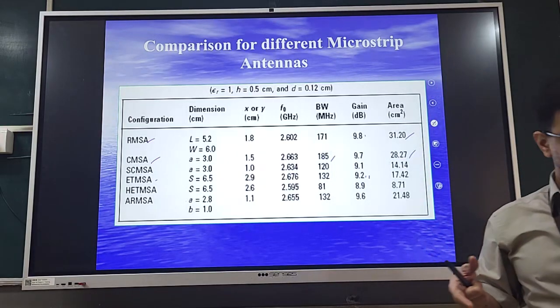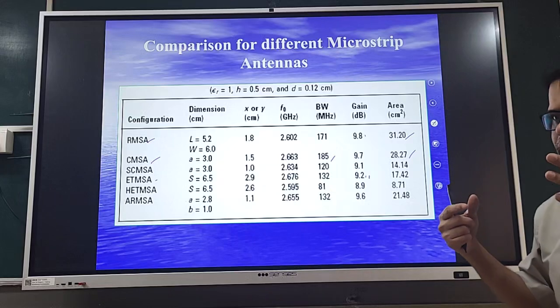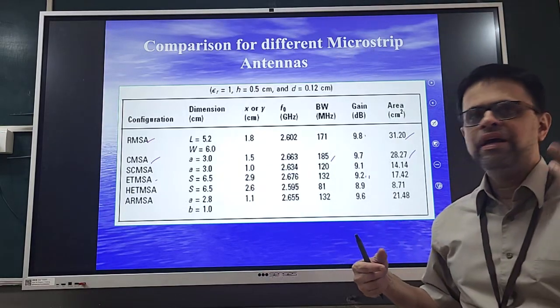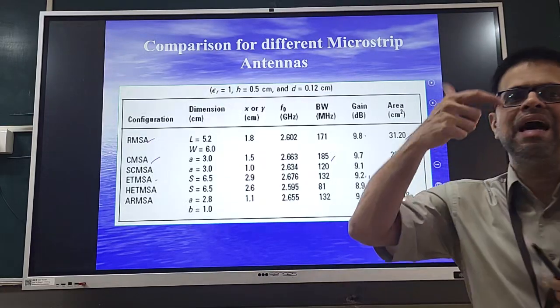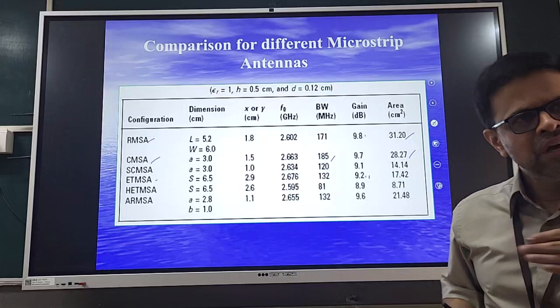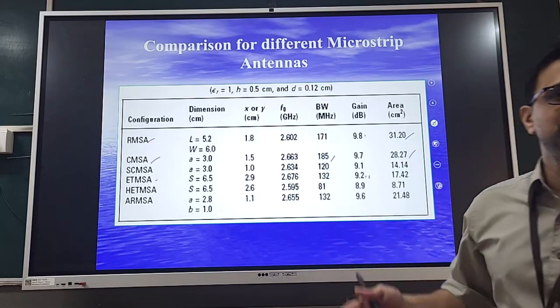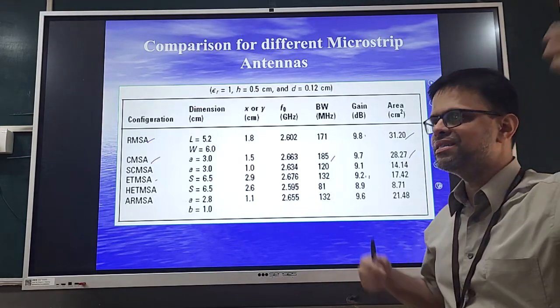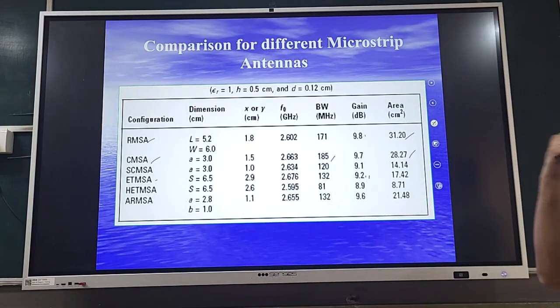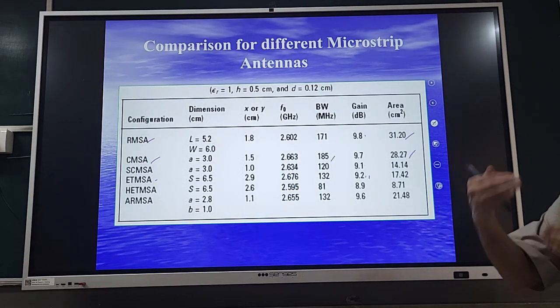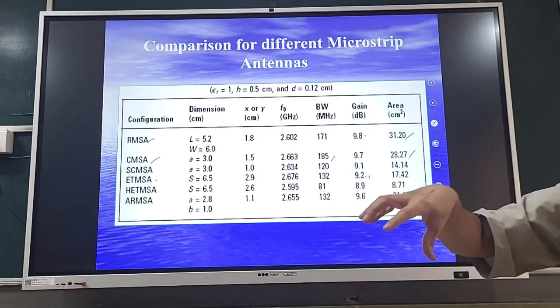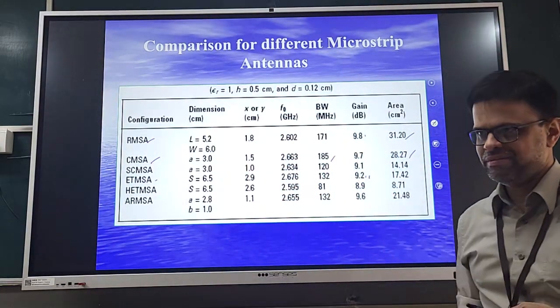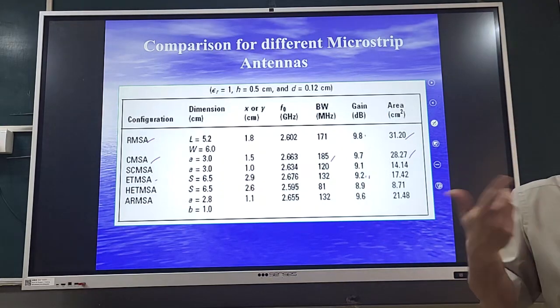Another question can be this way, that I want to design the antenna which should receive the signal in any direction, plus it should cover a lab-like distance. So when I say a lab-like distance, that means I require a low cost solution and a low gain antenna. So FR4 will do. If I want to cover a larger distance, I require an efficient antenna. So RT-Duroid, air, foam or other kinds of substrates have to be used. So likewise, by doing a proper blending of the practical applications, we can address the problem statements. So a more practical approach has to be brought into this.